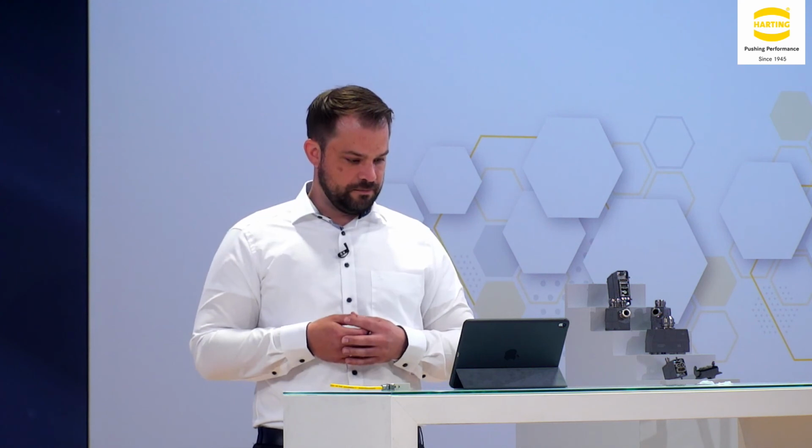Generally, our pneumatic module is qualified for pressured air, and therefore there's always a risk of resistances in materials. And of course, we have to make sure that the gas that you transmit is not flammable because of the electricity within the connector and the sparks that can be created. We have to be very careful with that.